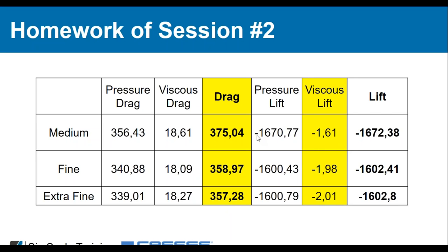And this is what we call a mesh-independent solution. To be honest, the tutorial was not a mesh-independent solution at all. The quality of the results is good enough to get some first insights, but if it were really about absolute values, for sure you would have to use a finer mesh. The reason why we chose this coarser mesh is that this is still a tutorial, and our aim was to deliver the fundamentals of simulation that make you able to set up your own simulation. But for sure it is recommended, or possible, to make the mesh finer.